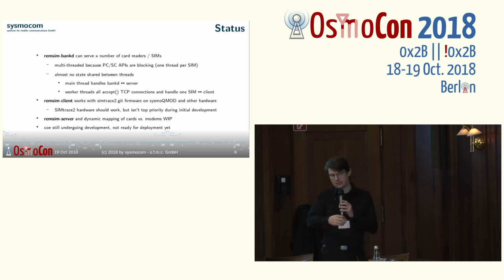to respond. And if the card is not finished supplying that response in time, it can ask, using I think 0x60 hex or whatever, for more time. It can say, oh, I need more time, I need more time. And according to the spec, there is no upper boundary how often you can do that. There is no maximum number of waiting time extensions. Of course, in reality, the baseband stack of the phone will give up at some point.